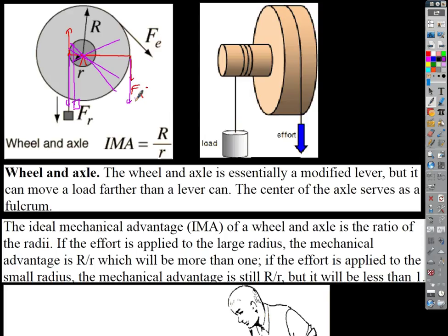And I think that even happens with most cars, even if you're driving down the freeway. I know on good cars it is. The effective gear ratio changes with speed. So if you're going really fast, ideally, if you turn through a big angle with your steering wheel, do you really want the wheels turning very far? No. Because you never should turn the wheels beyond a certain angle, or you're going to flip your car, right? So it actually gives you a mechanical disadvantage after a while, the steering. So with really fast cars, you can control where you're going more precisely because you can turn through a bigger angle and have the wheels barely turn. And as you go slower, it'll change the effective mechanical advantage.